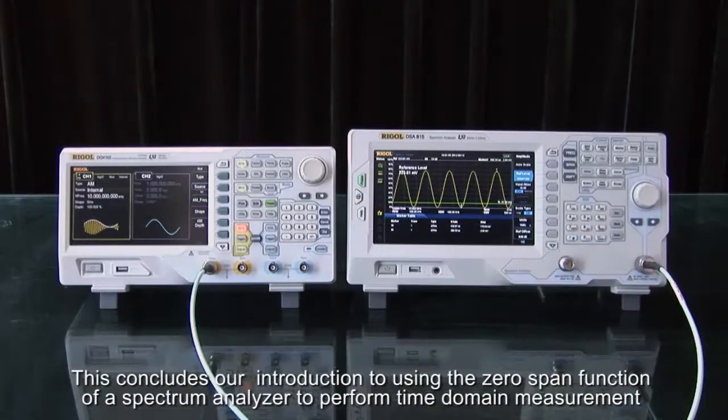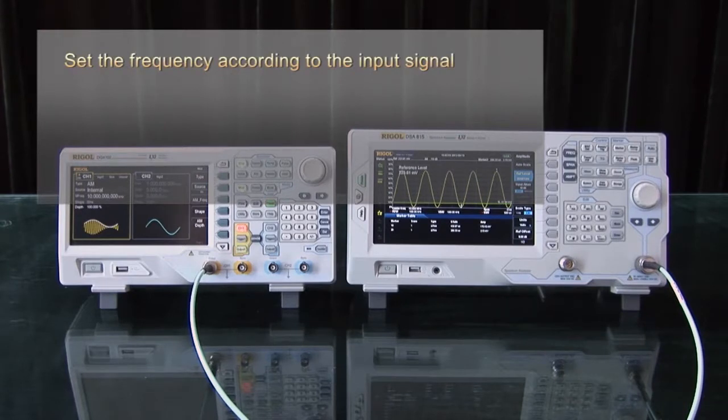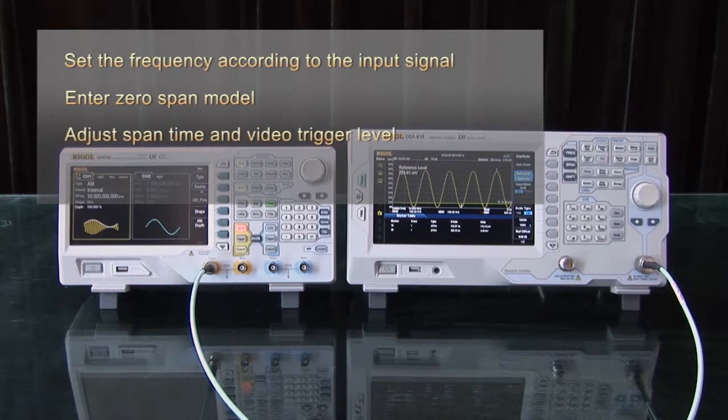This concludes our introduction to using the zero span function of a spectrum analyzer to perform time domain measurements. Here are some notes. Set the frequency according to the input signal. Enter zero span mode. Adjust the span time and video trigger level, and then use marker functions to perform the measurement.